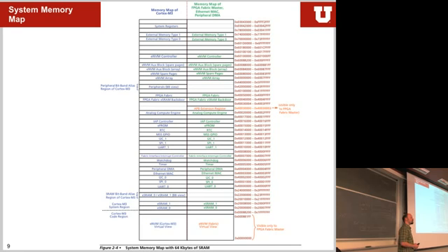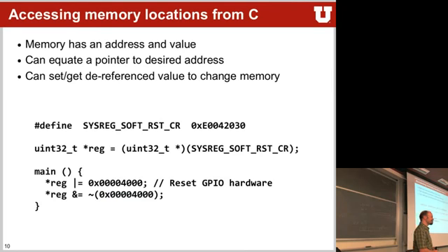Yes? Are there nice assembly header files that define human readable aliases? No, that's when you use C. So you can do the exact same thing in C. Now, how do we tell C where a variable is located? We give it the address, exactly. So what type of variables do we have to use? Pointers. Exactly. Pointers are addresses in memory, right? That's all pointers are. So this is how you can address a memory location using C.